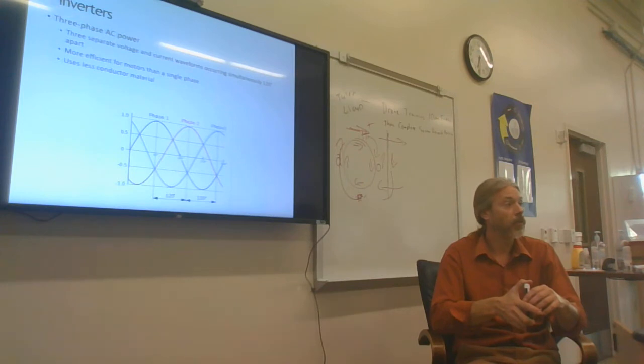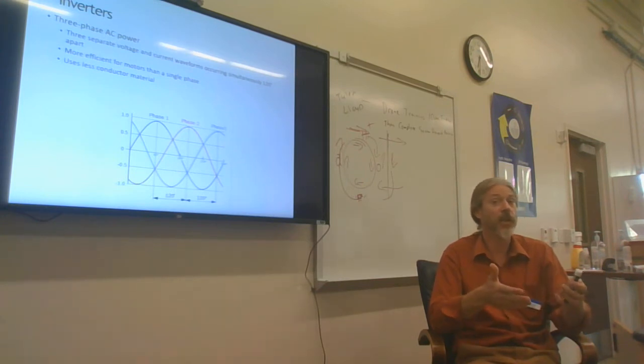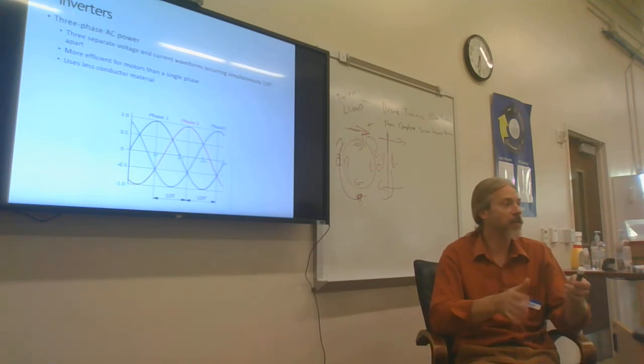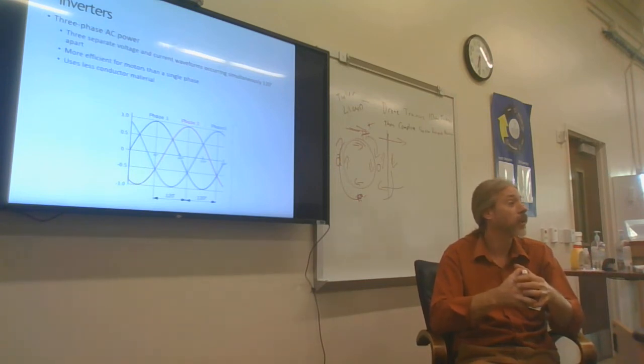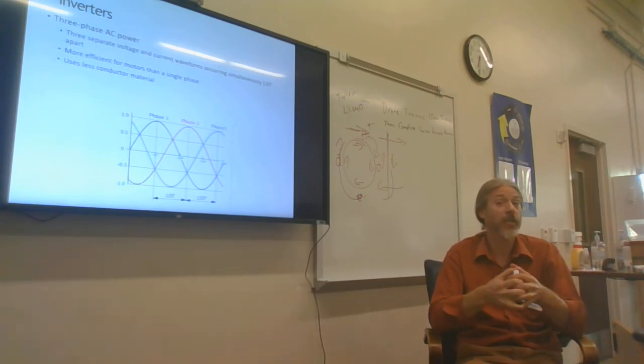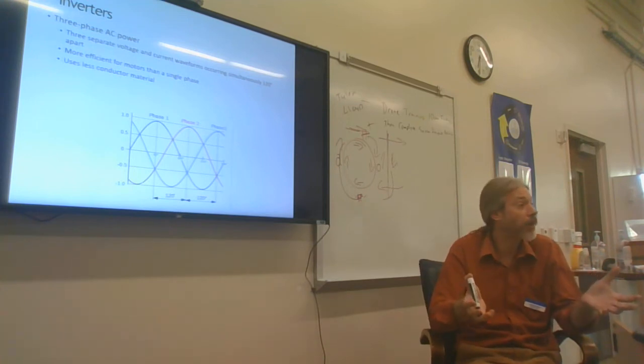Anytime that you can go with a 3-phase inverter for a project instead of 3 single-phase, do so. We have a customer right now that is putting in a 20 kW system, but they do not have 3-phase electricity at their location. I could buy a 32 kW inverter cheaper than I can buy 20 kW of single-phase inverters for this customer. 3-phase inverters are larger, normally 30 kW or bigger, but their cost per watt is significantly lower. And they're really easy to wire.